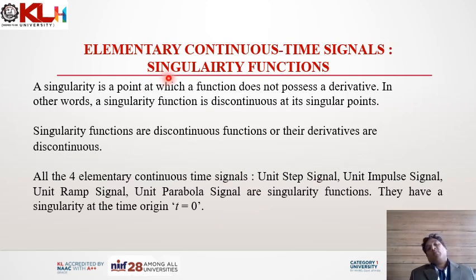Now we are going to discuss the singularity functions. Singularity functions are discontinuous functions and their derivatives are also discontinuous. So a singularity is a point at which the function does not possess a derivative. If the function is discontinuous, then it can be said to have a singularity at the point of discontinuity. Now, if you see all the four elementary continuous time signals, unit step signal, impulse signal, ramp, and parabola, they are all singularity functions. They have a singularity at the origin, t equal to 0.